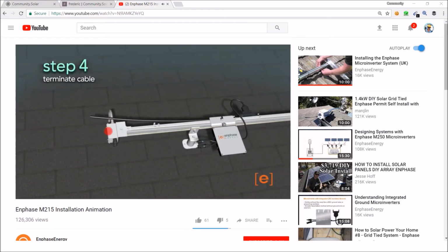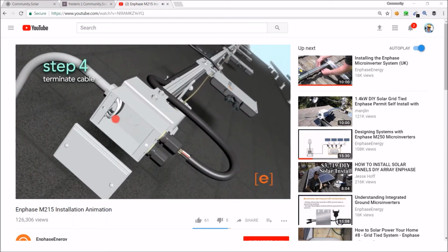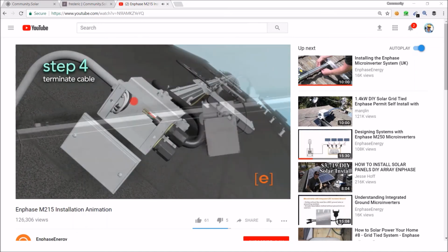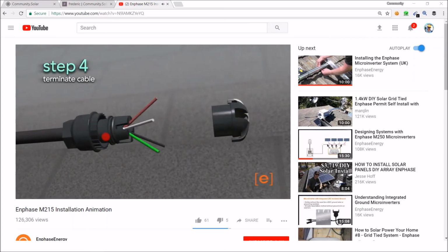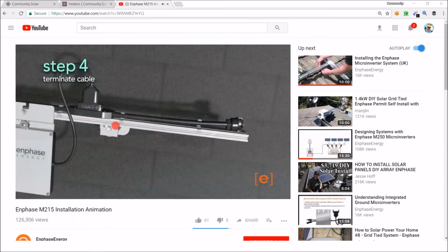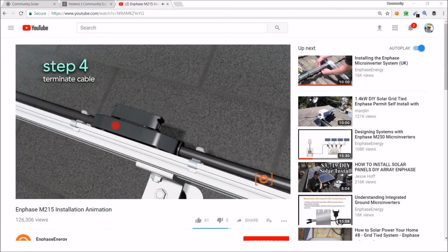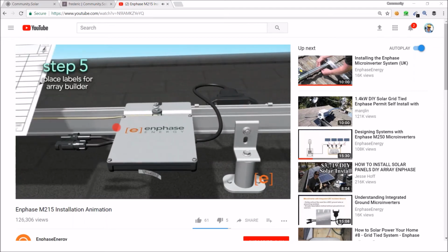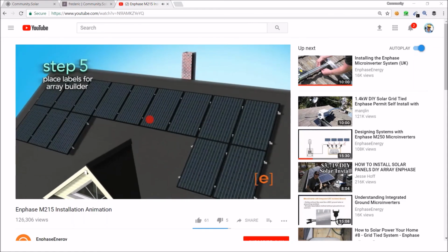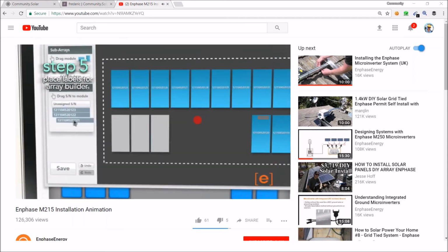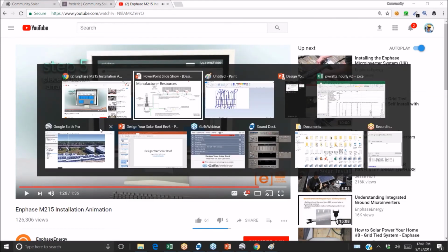And then here we're just going into a roof mounted junction box, running our tray cable into the junction box, and then maybe landing on a terminal block with our wires. And as we talk about in our National Electric Code class, the main thing on how do I know what wires to select, it all comes down to their temperature rating and their environmental rating. So the wires inside your home are rated for dry conditions. The wires that you need to run up to the rooftop need to be rated for wet conditions, and exposed wires need to be rated for sunlight resistance. And now they're setting up the monitoring system.